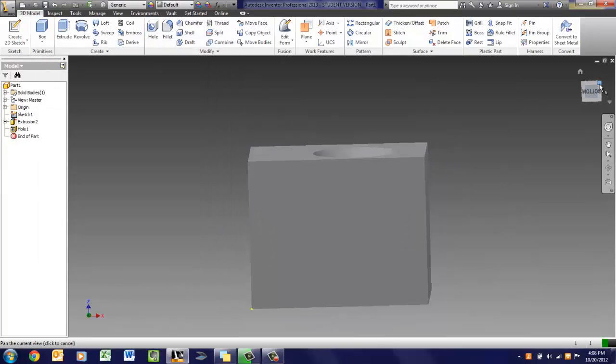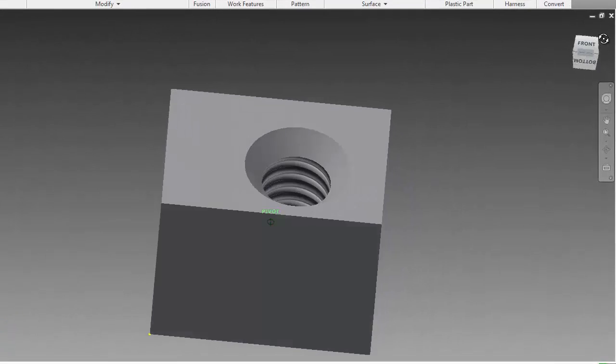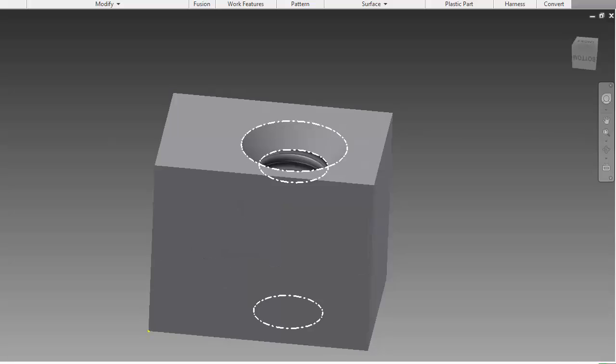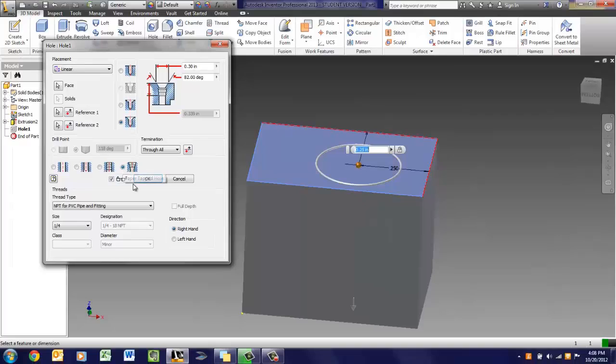And if you notice, at the top is countersunk. Then if you look down inside, you can see the threads that would be applied to that space. Okay. But again, I can go back in here, and we all know that if we double-click over here on our model browser, so say I want to adjust my hole, okay, I can double-click on hole and come back in here, and I can do something different. So the other options we have are, okay, that's a taper tapped hole. So the taper would go all the way, the tap would be set up based on this taper, or we could also do clearance hole.